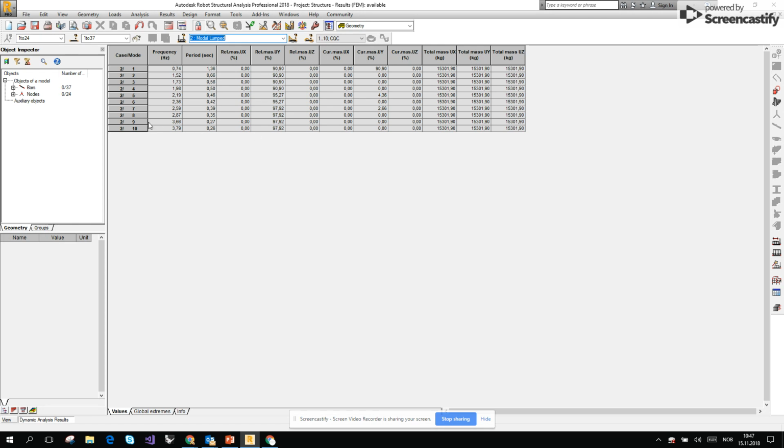This is why I have to check more modes than just 10. I will check also the consistent type of the analysis, and I see that the values of the relative mass have changed, but not so much. Let's see that for the 10th mode, it's 462, when for the lumped, it's 379. So for the lumped, it's a little bit smaller, but for example, the first mode is almost identical for both. At the second, it's already quite different because it's from 152 to 161.